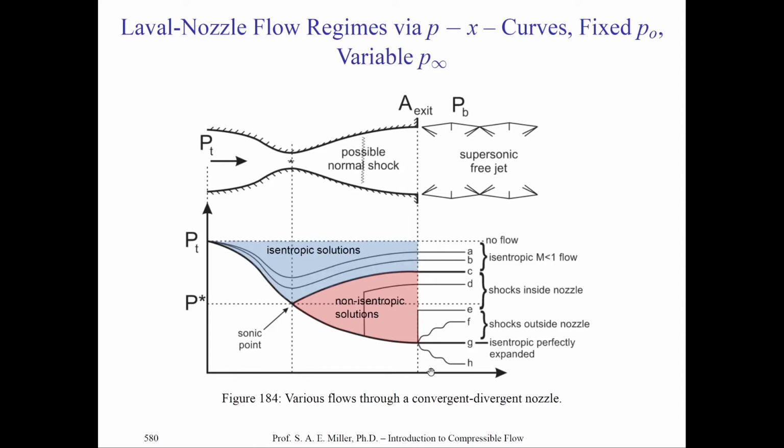Now you can see there's actually an infinite solution of different nozzle pressure ratios for supersonic flow through the nozzle, where you have shocks and expansions and shocks vice versa through the nozzle exit. These little double lines represent perhaps expansions, and these lines here, which look like little triangles up and down, hats and inverse hats, are the shear layer of the nozzle. We'll look at this more carefully later in the class.